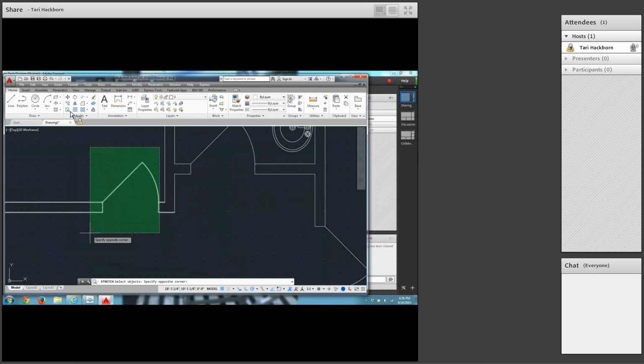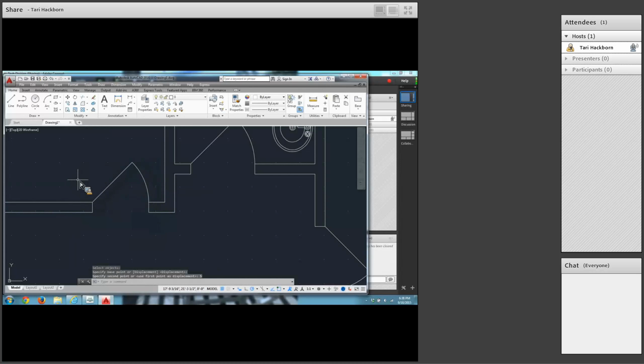You know, you want to make sure that you're over far enough right here. Okay. Enter, click, drag this way, and type 5. So it could have been in 2 operations. And the door opening lines and the door swing, they were all inside of the green window because they just have to be moved with everything else. They don't have to be stretched.